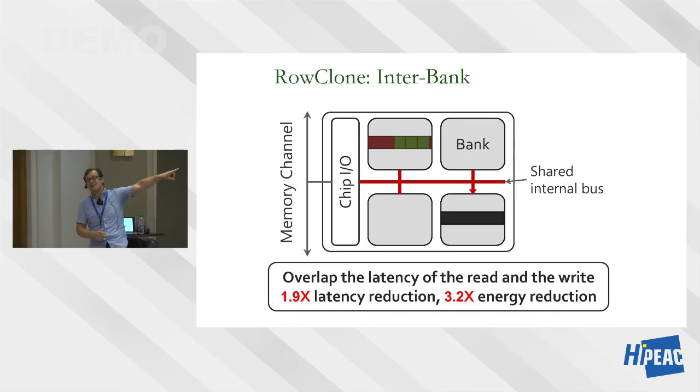Here, they're not sharing the sense amplifiers. Here you have to go through an internal structure: you're doing a read from an internal structure inside the DRAM and a write to another internal structure inside the DRAM. But you're not going out of the chip. You're not exercising the huge chip I/O pads.